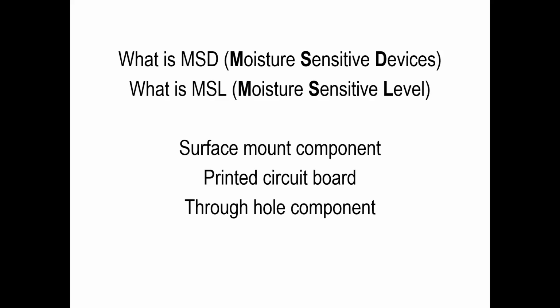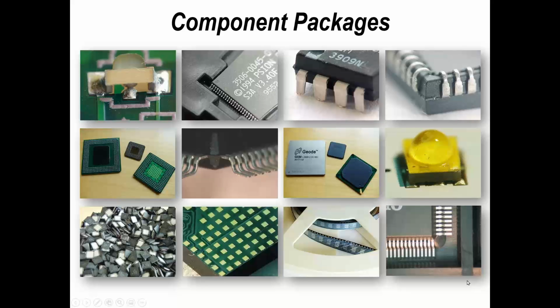Now, if we look at through-hole parts, it is possible that during rework and repair, and also if you're using some parts with intrusive reflow, this is pin and paste reflow, then again, moisture sensitivity may not be documented from the supplier, but it may be something you need to consider as well. So if we just look at surface mount components, as you know, there are a myriad of different parts, and generally speaking, we're talking about plastic packages, but also packages that are partly plastic, partly fiberglass in their construction, like area array and BGA packages can suffer from this particular problem.